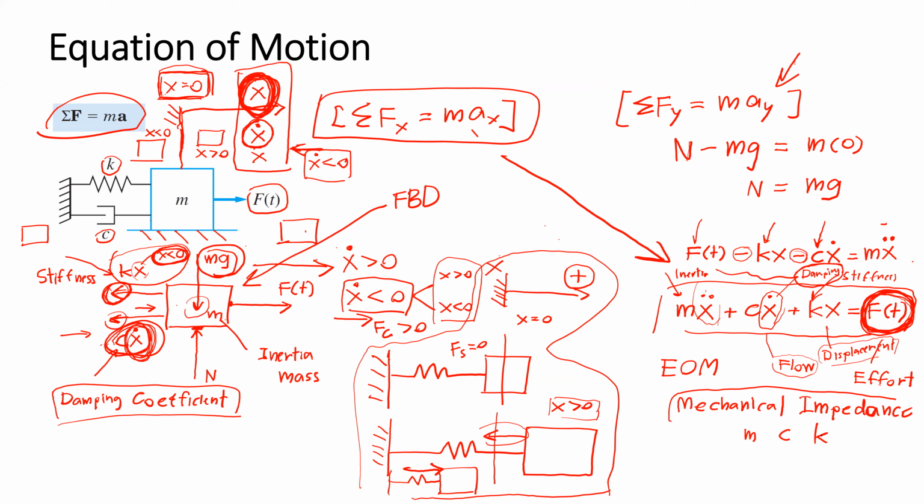The motor to drive the robot can create some amount of torque. But if we want the motor to carry a big load, the direct solution is we just add the gearbox to the motor so that the motor can have a bigger torque to drive the system, to carry the load. But if we add the gearbox to the motor, we are adding inertia to the motor.